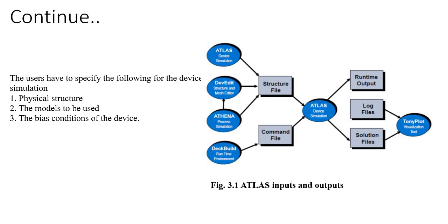Atlas, DevEdit, Athena, and DeckBuild are the integrated parts of Silvaco TCAD. So Atlas is the device simulator, okay? And with DevEdit, you can create the structure, you can mesh that structure, and also you can run process simulation of that structure. Now that you have created a structure file, it goes to the device simulator, and it will provide the runtime output with the solution files. So this is how your Atlas device simulation will work.